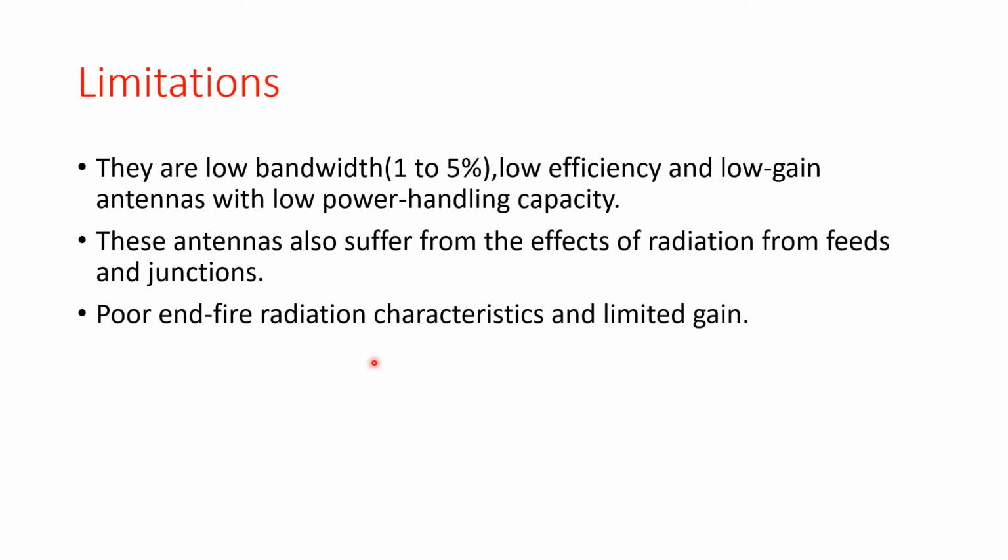First limitation is its low bandwidth. That is, as I've told you, it supports a maximum of 1 to 5%. Also it has only very low gain with low power handling capacity. Also they suffer from the effect of radiation from feeds and junctions. Wherever we are feeding, there are possibilities of radiation, and also from the junctions. And this provides very poor end-fire radiators.